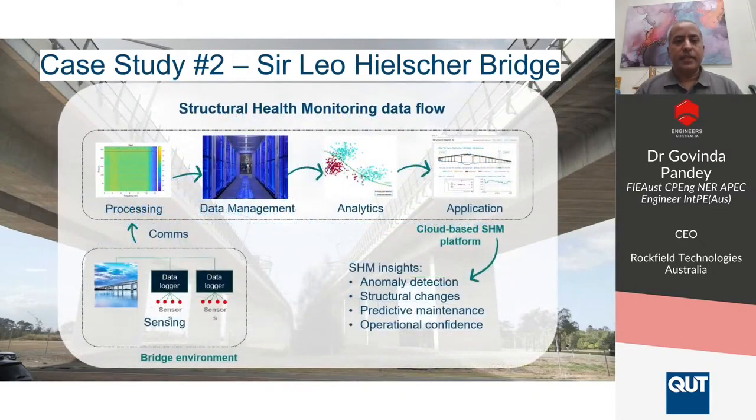We implemented a structural health monitoring system into that bridge. This is a collaborative project, and the system is that you put a sensor network into the bridge, and through comms you then transmit data to a cloud instance. You process the data, do the data management, run your analytics.